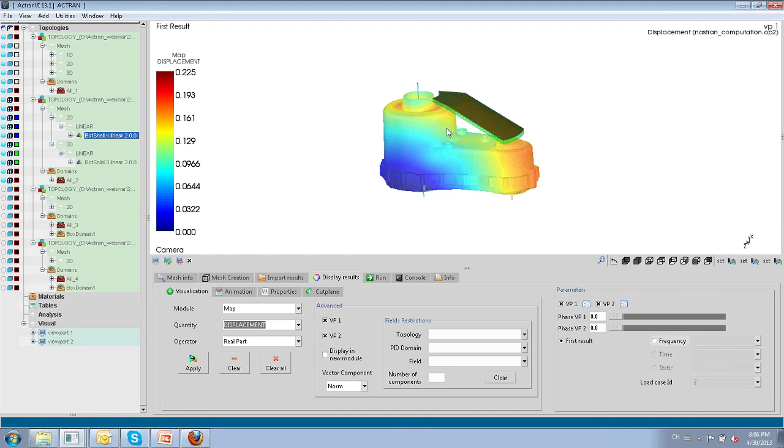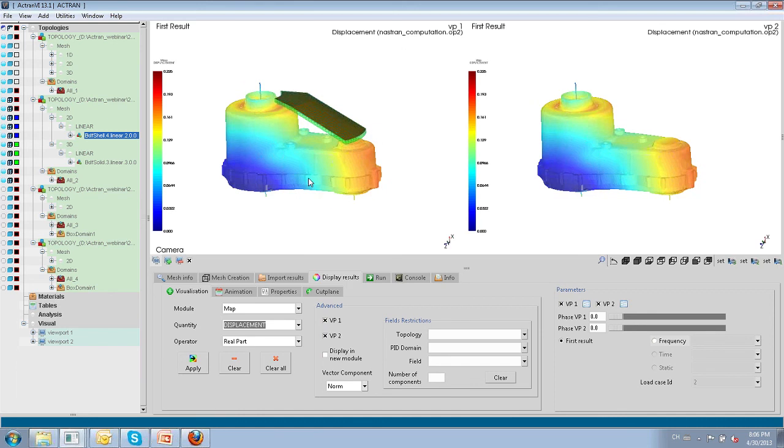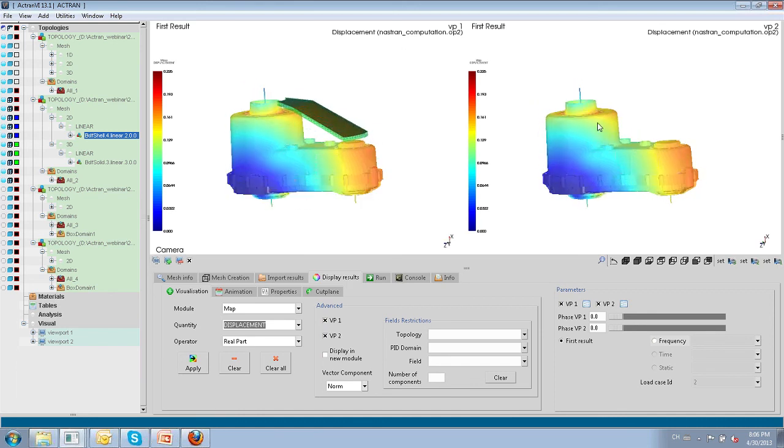To account for the effect of this cover, we need to use the fully coupled vibro-acoustic solution in Actran. And then we can compare the result of this problem with the result of the gearbox radiation without any shell or any porous material covered on it.